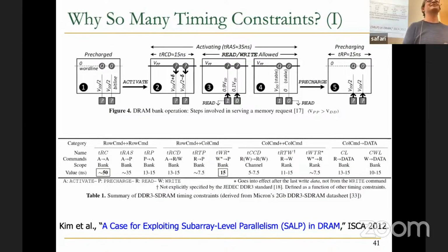Atabak, do you have anything to add about the alert command? Do you know when it's used, how it's used? Yes, so that's basically a kind of negative acknowledgement. But it's not clear when you receive the alert, right? It may be a bit too late. You may have actually proceeded a lot, right? So the protocol is really not fully optimized for robustness, I think. It just assumes things are done. We can talk more about that later on. There may be errors happening at different places where alert may not be able to catch those errors. But these are good things to think about: how do you design a better protocol?